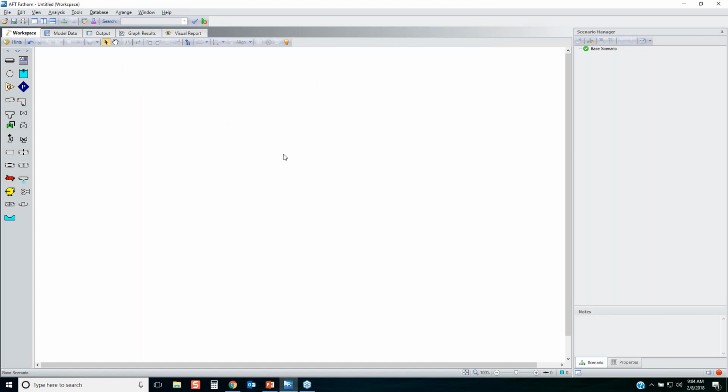The next thing that you want to do, when you're not sure where to start with the model building process, is focus in on the status light down here in the bottom right-hand corner. Red means stop and green means go. And so if you go down and you click on that red status light, it's going to bring up a checklist of items that need to be completed before you can run your model. So let's just go through these together one by one.